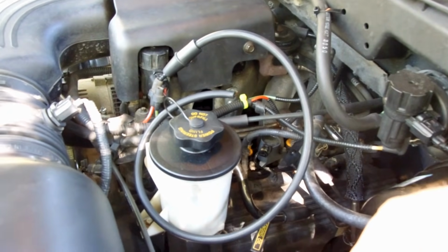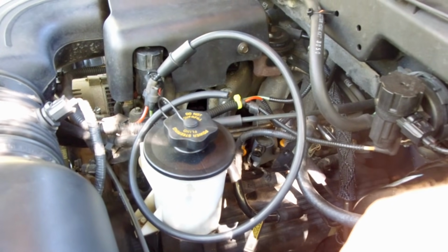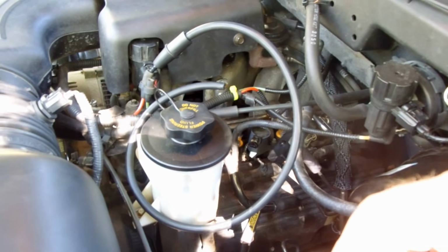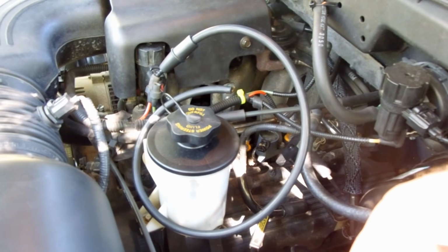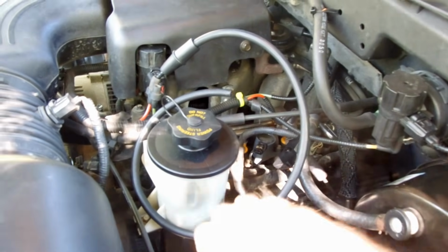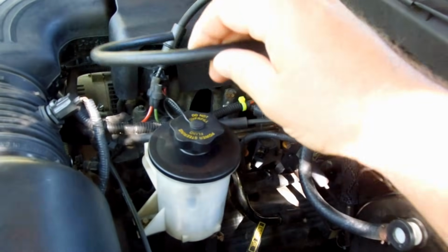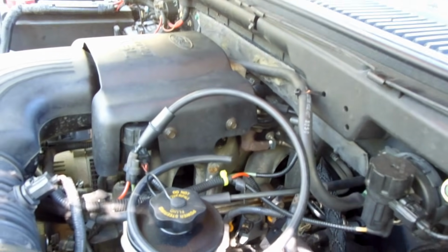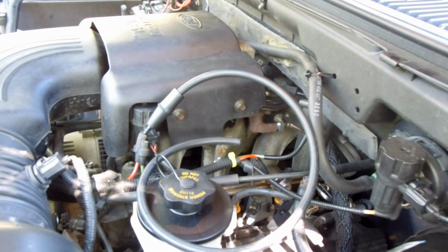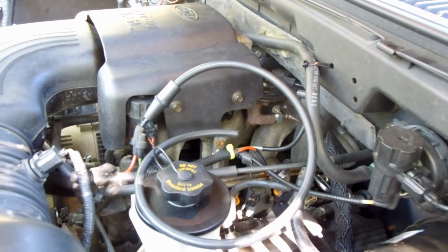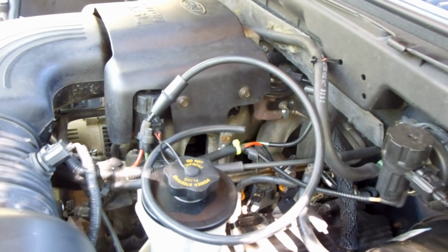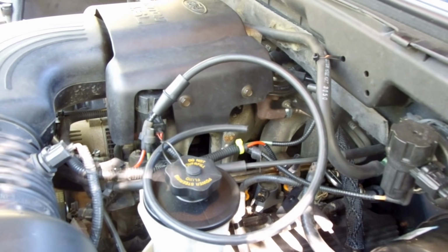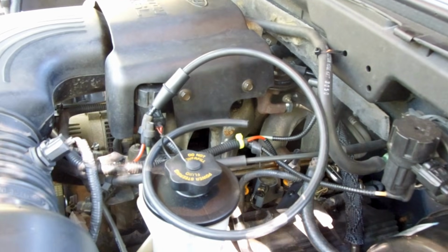Hey, we're back outside, and as I noted, this F150 has just come from the shop, and they completely cleaned the EGR ports on that throttle body, so the system is working as it was designed to work. And what I want to do is I've hooked up my vacuum hose to the source vacuum again. I'm just going to go ahead and put this on top of the EGR valve like I did before. Now with this thing working properly, this engine should either stall or just about stall at idle when you apply vacuum to that EGR valve. So I haven't cheated, I haven't tried this myself yet. Let me go ahead and put the camera down and start the engine, and we'll see what happens.